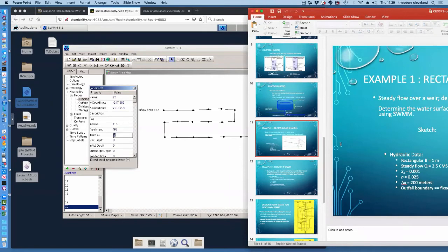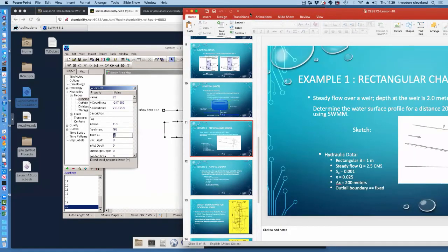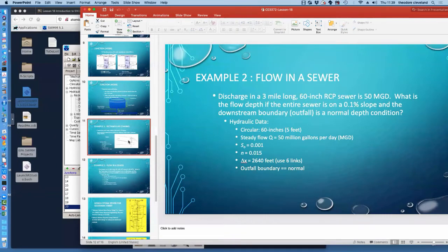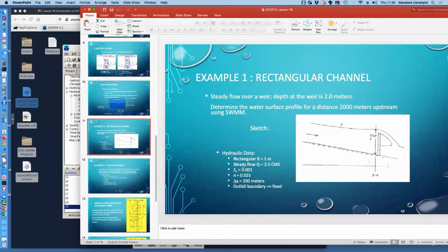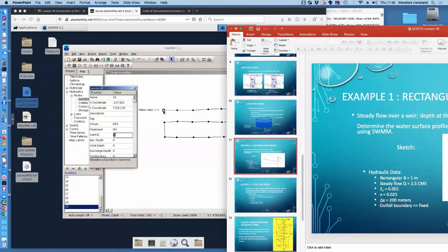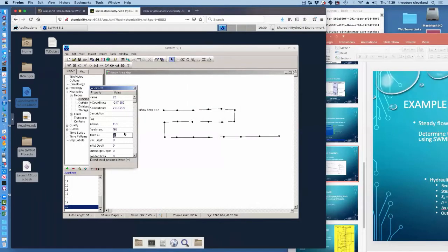And our slope is given as 0.01. So 3,800 times 0.01 should be, that's 1 part in 1,000, so that'd be 3.8 parts. So this should be elevation 3.8. So we would go ahead and tell it that it's 3.8.